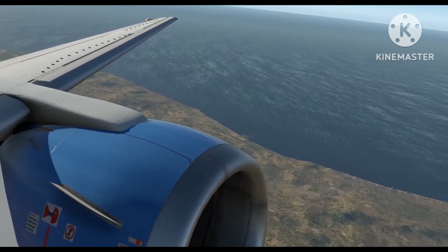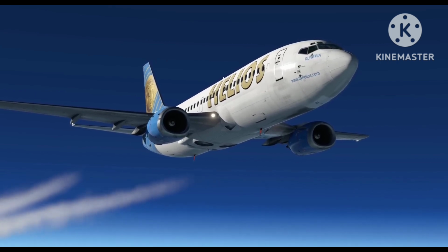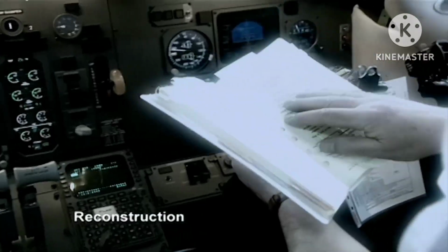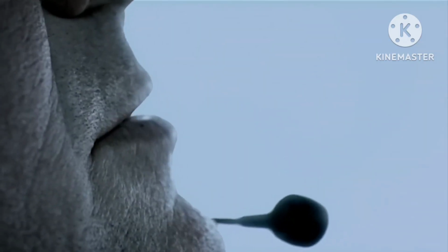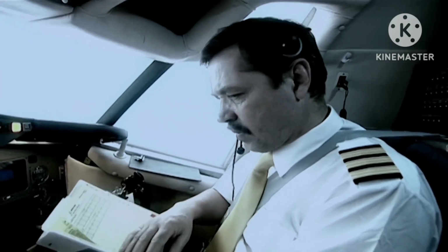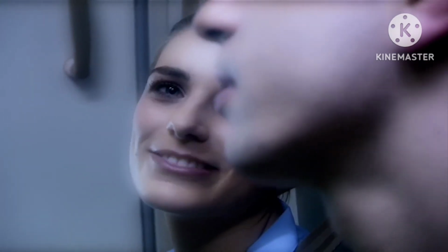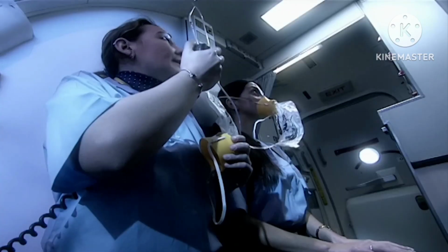Alongside dealing with alarms and warnings, this additional issue may have distracted them from recognizing indicators such as the unexpected deployment of passenger cabin oxygen masks, which were crucial signals of the ongoing depressurization. The cockpit, although part of the same aircraft, is equipped with different ventilation and pressure monitoring systems compared to the passenger cabin. Due to a pressurization system issue where the pressurization mode selector was incorrectly set to manual instead of auto, the cockpit did not reach the altitude threshold required for the automatic deployment of oxygen masks. Consequently, the masks in the cockpit did not deploy automatically.